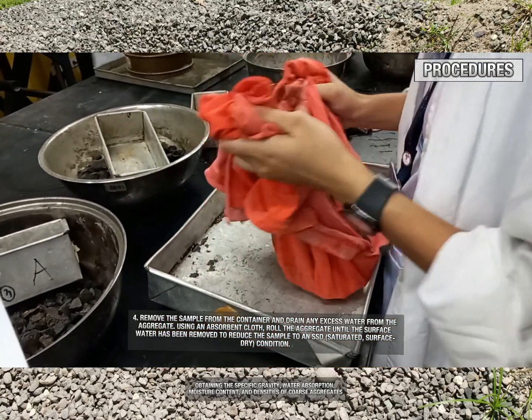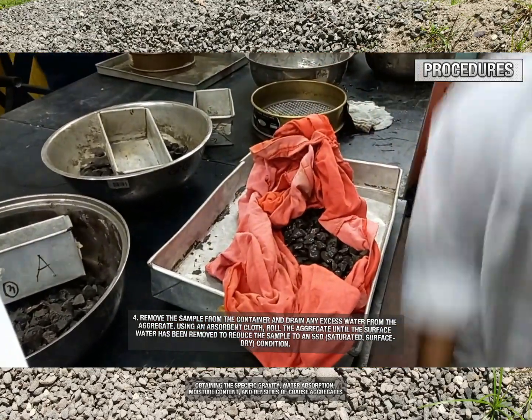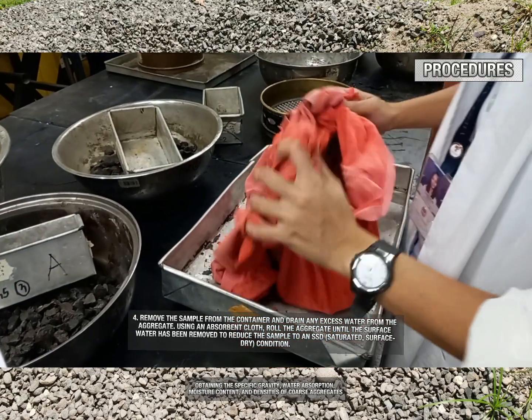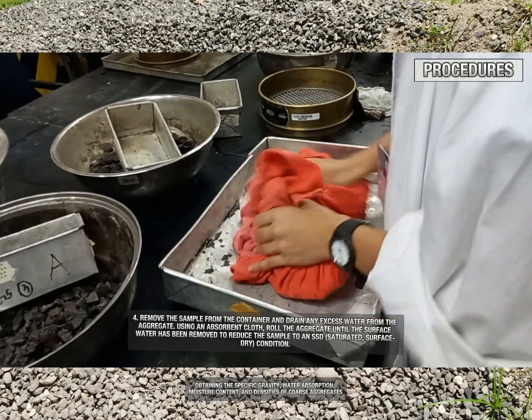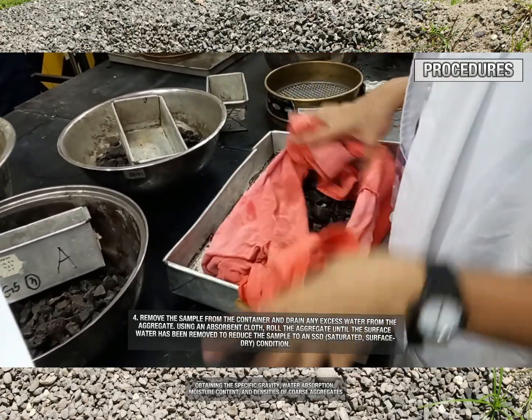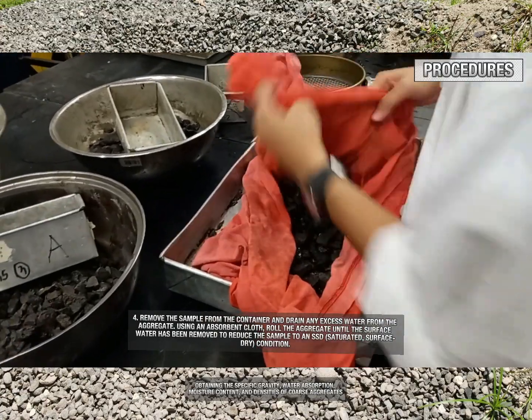Using an absorbent cloth, roll the aggregate until the surface water has been removed to reduce the sample to a saturated surface dry or the SSD condition.